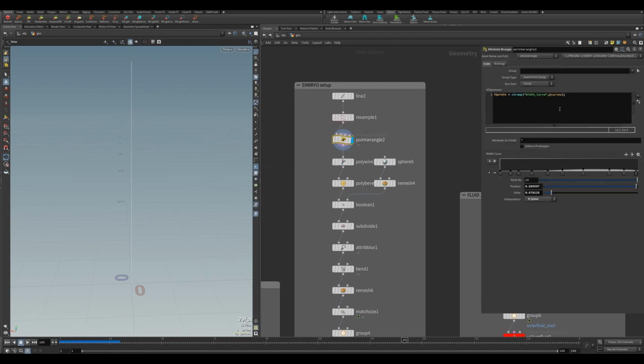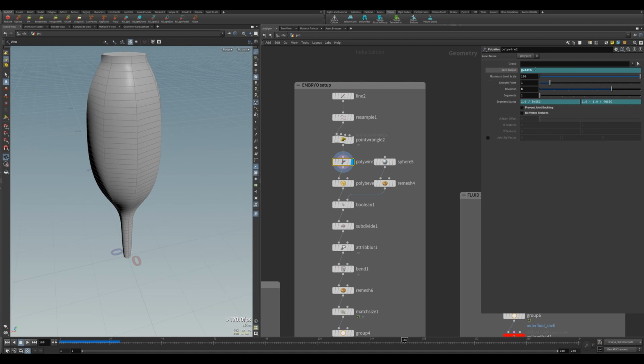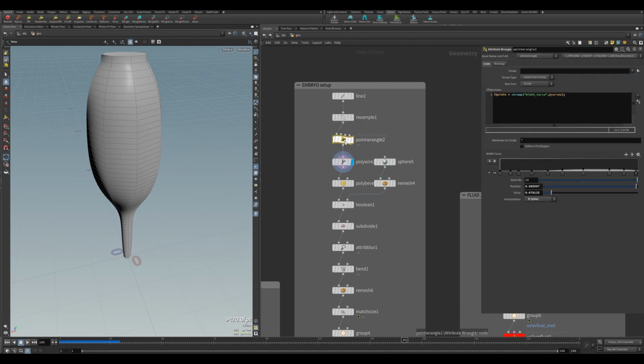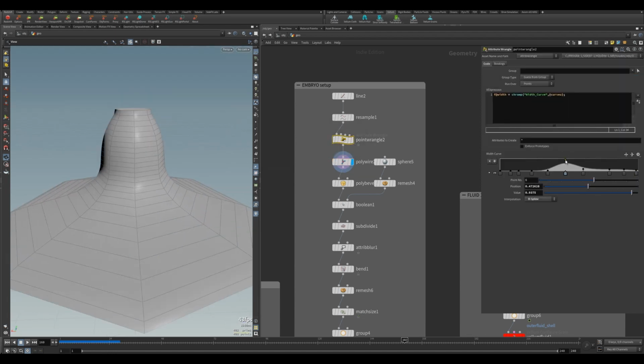And I'm using that to create this width attribute with a channel ramp function, using @curveu, because you need an attribute here which is normalized. If you don't have that, the ch ramp function will not work. Once you type this in, you click on this little icon here, and you'll get this ramp, which you can adjust. You're not seeing anything here yet because I'm using it on the poly wire, and then you'll see it. The wire radius is @width, which is the parameter I generated here. Of course, every time you adjust something here, you can see it changes.